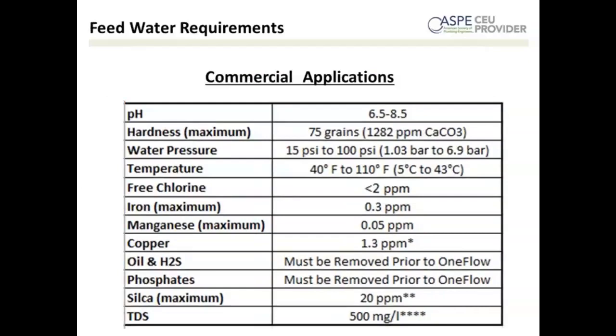Okay. Follow-up question on using Watts TAC on cooling tower. The question is, if TAC has been installed on the makeup water to the tower, not TAC on the recirculating water in the tower, removing minerals from the makeup water to the tower can reduce the blowdown and treatment rates of the recirculated water in the tower. But keep in mind, we're not removing minerals, right? We're converting minerals to grow microcrystals to bind to each other. So there's a misunderstanding on the fact that TAC is not removing minerals on makeup water.